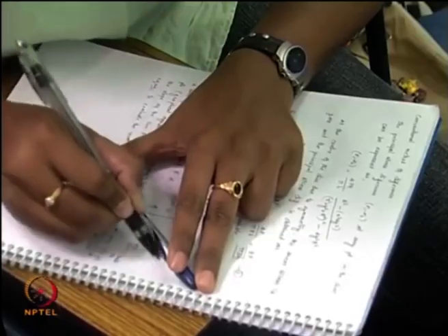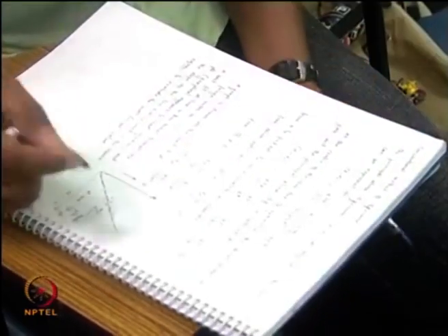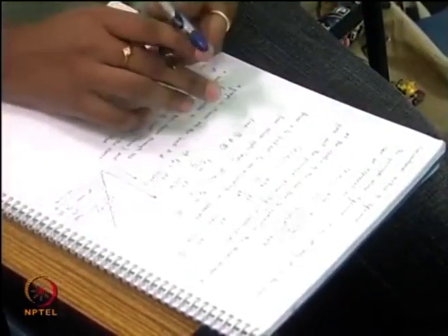And I can find out n accurately by Tardy method of compensation, where I have to just rotate the analyzer for each load and find out the fractional fringe order. I also mentioned earlier, in early days people had a very complex loading mechanism, wherein they would adjust the load so that the fringe passes through the center. The data point here is the center of the disk.